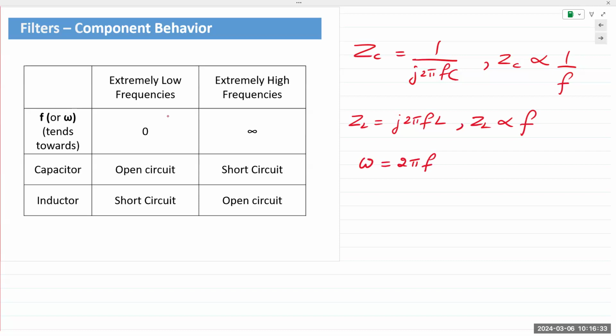You have a time domain expression, right? Frequency f in hertz, and you translate that as a vector, its angular frequency in the frequency domain. So omega is 2 pi f. One full circle, 360 degrees, 2 pi. Hence, omega is equal to 2 pi f. So it's the same exact equation.